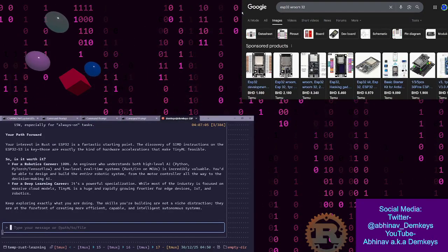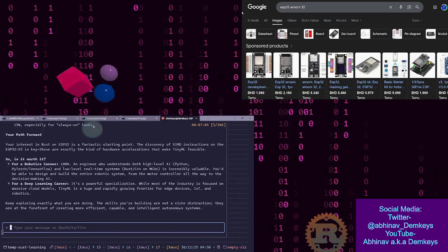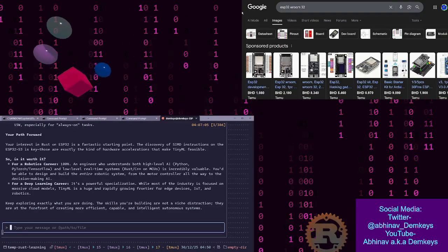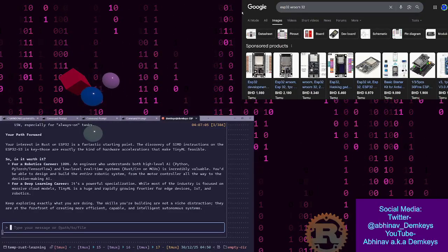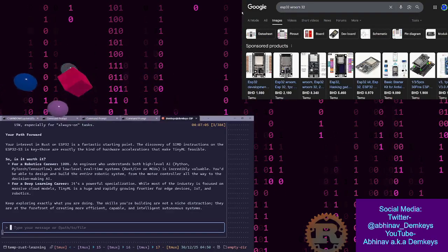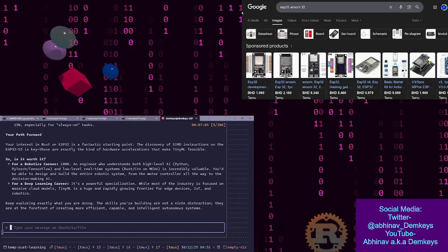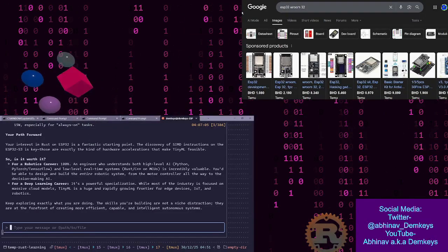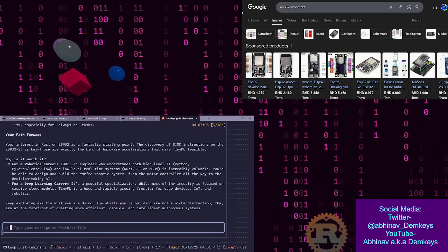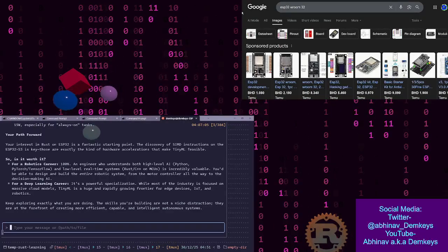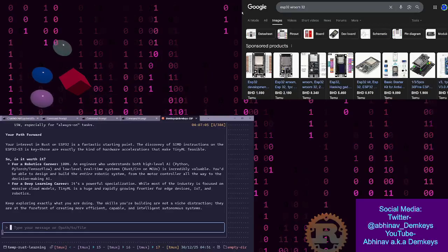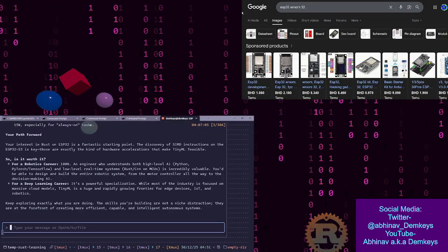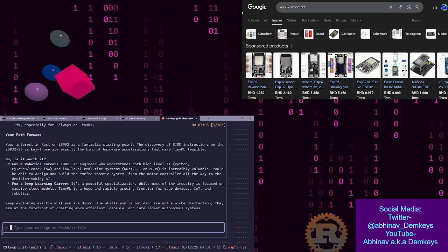All right. The Super Mini dilemma. The ESP32C3 Super Mini is different because it often doesn't use a metal shield to save space. The MCU location: look for the small black square chip on the top of the board. It's usually about 5 by 5 millimeters. This is the actual ESP32C3 SoC. All right. Heatsink placement. Because it's so tiny, a traditional finned heatsink is often overkill and physically difficult to mount.